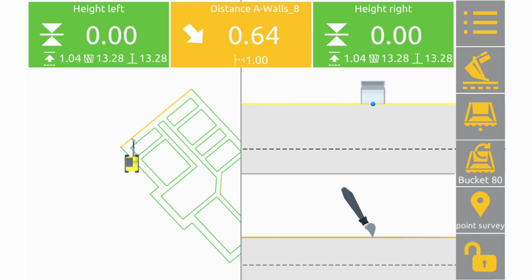solid yellow line. That's our level. That's the level that we always work to with the machine control. We always work to that yellow line, and the middle of that yellow line is level, and slightly above and slightly below is maybe 20 mil off of level, yeah.